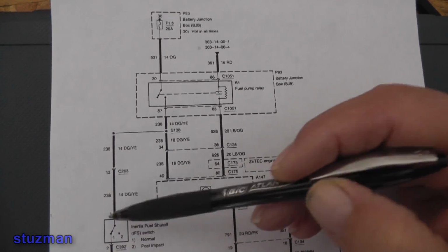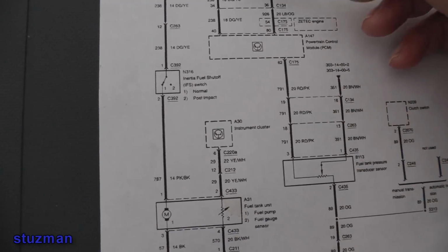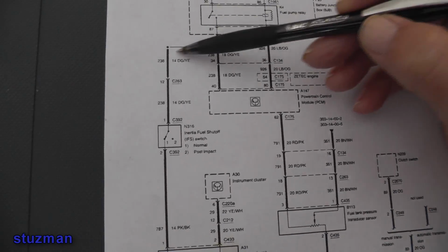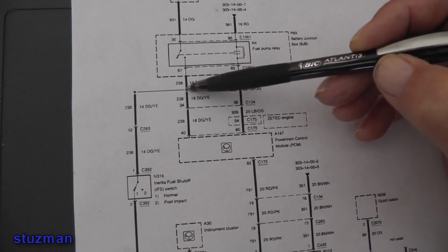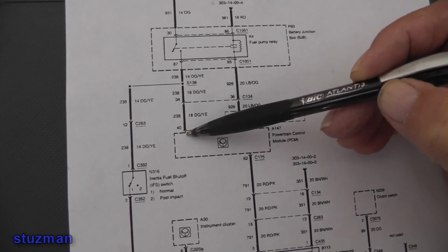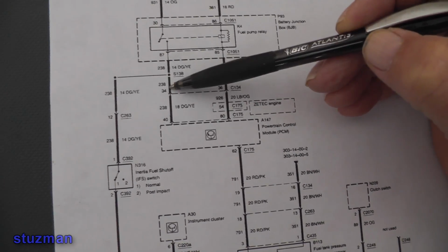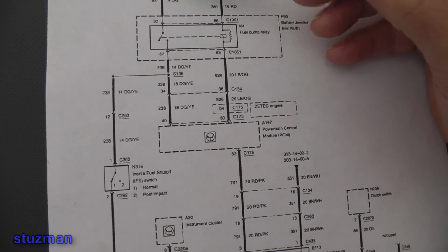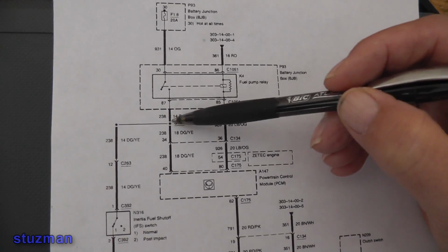This is going down through the inertia switch, also going down to the fuel pump. Okay? So we have this current path here, and we also have this current path, here's like our node, our splice point. We have current coming down to here. So if we take these two currents, add them together, that's going to be equal to this current that's being supplied to this node or splice.